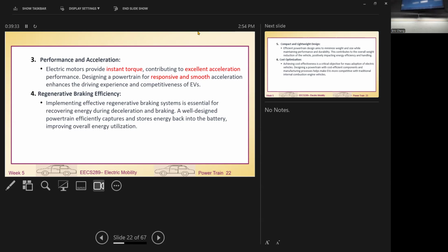Did you see my answer for homework one? Yeah, 1.83 only when the friction coefficient goes up to 1.5. You are able to have 1.83 seconds acceleration time for 0 to 100 km per hour. So I don't think any vehicle is able to be less than 1.83 seconds for that acceleration. That is also the limitation for the acceleration. So if in the future somebody sells a vehicle and says my vehicle's acceleration from 0 to 100 km per hour is 1.5 seconds or 1 second, impossible. That's beyond the physics. Impossible.